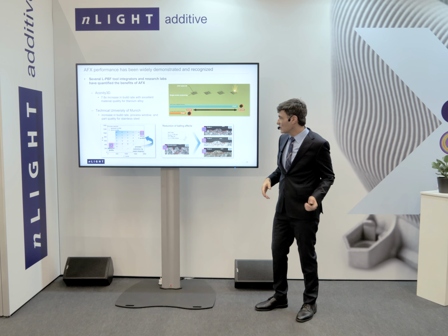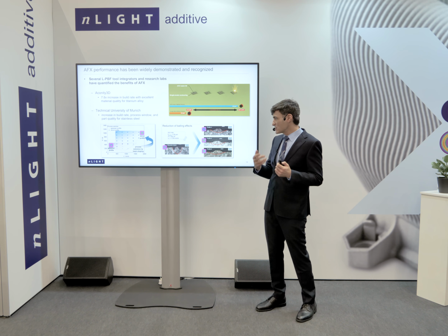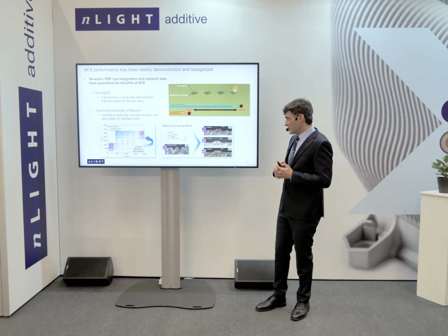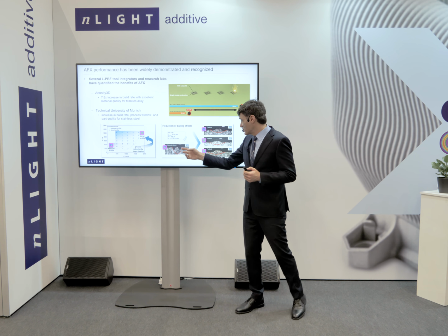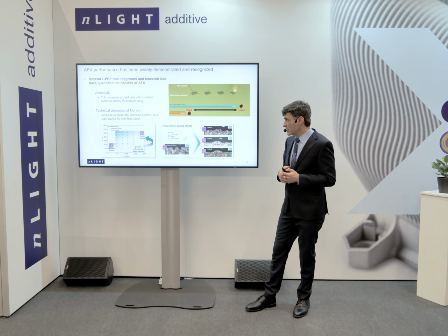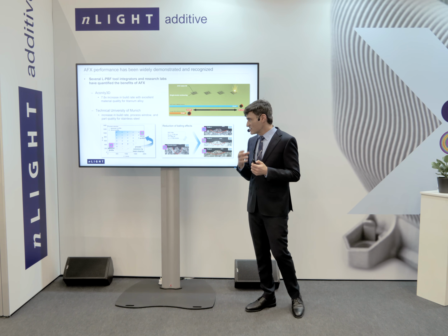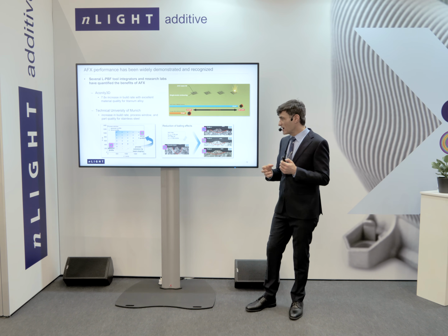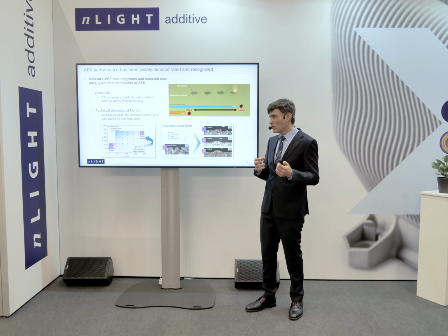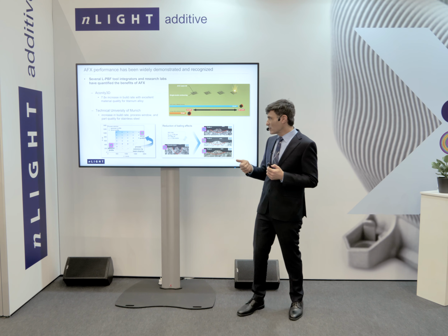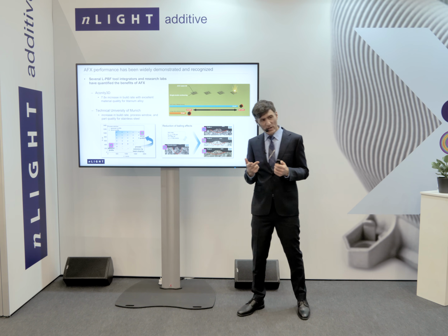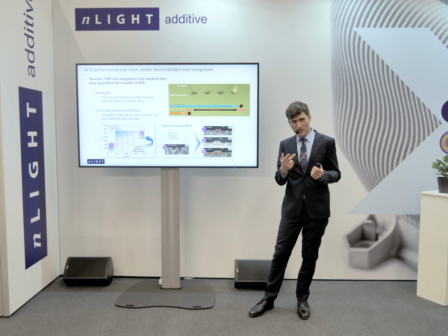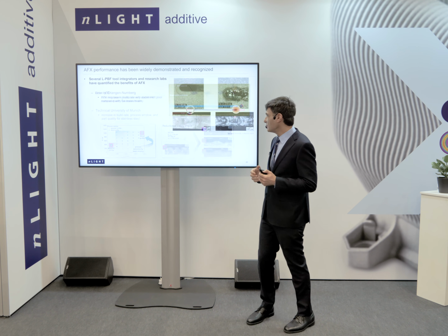In fact, when they look at the part quality, much as I showed you earlier for Inconel, they show this really reduction of balling effects when they went to the ring beams. So what you're seeing here is there's not a trade space where you're trading off speed or process window or quality. You're getting better build rate, better process window, and better part quality. So there's no real compromise here.